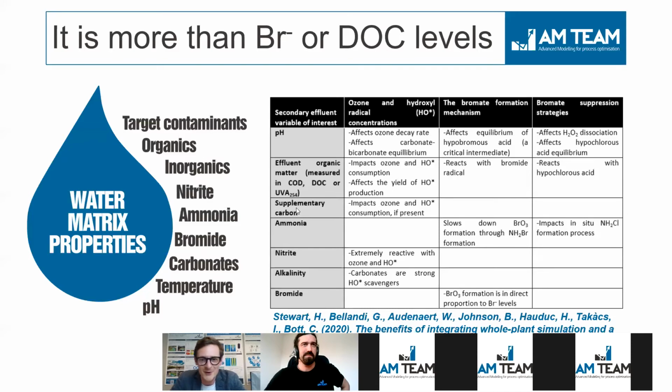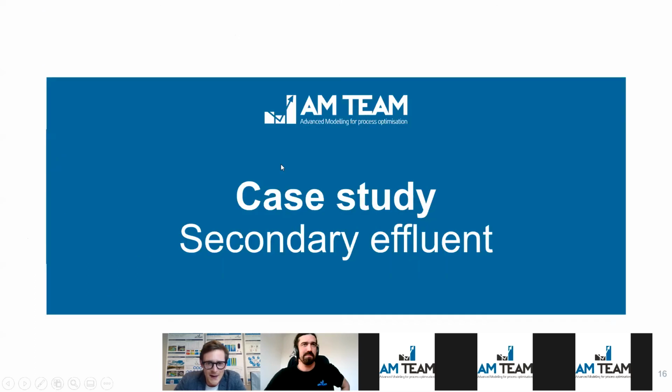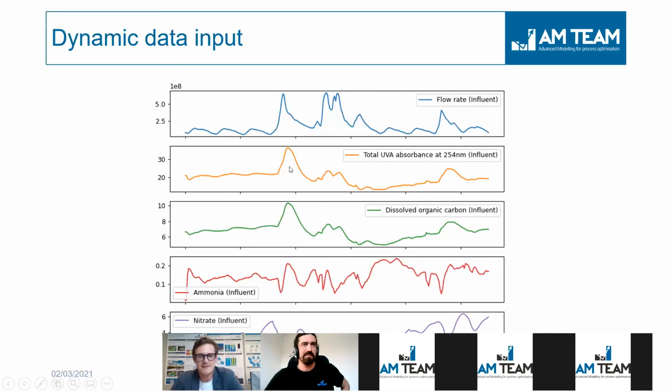Thanks, Giacomo, for the nice illustration of the full-scale plant dynamics. So Giacomo has actually shown these dynamics. Not a single plant is actually static, because everything is varying. Even drinking water has seasonal variations. If you look at wastewater effluent, it has more diurnal and weekly variations. Or of course, precipitation, rain is very important. In drinking water, the seasonal variations are very important. For example, ammonia and nitrification in surface waters have a big impact.